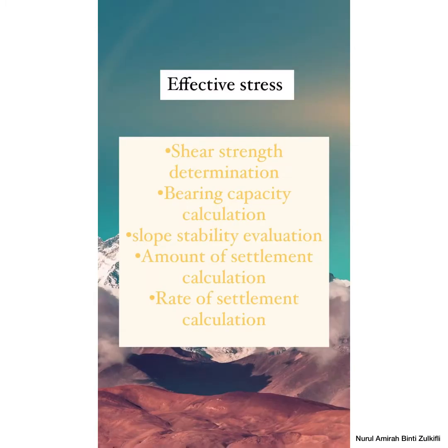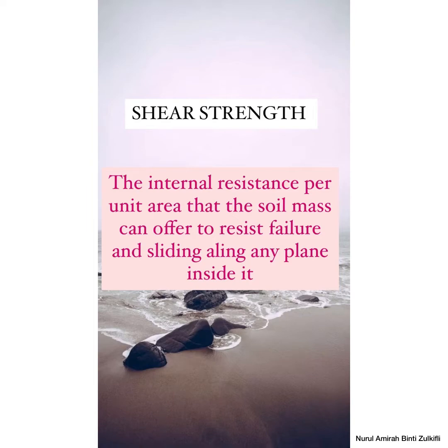So basically, why is effective stress important? First, shear strength determination; second, bearing capacity calculation; third, slope stability evaluation; fourth, amount of settlement calculation; and last, rate of settlement calculation. So what is the meaning of shear strength? Shear strength is the internal resistance per unit area that the soil mass can offer to resist failure and sliding along any plane inside it. It's along, not a link. So the meaning is internal resistance that can resist any failure and sliding.